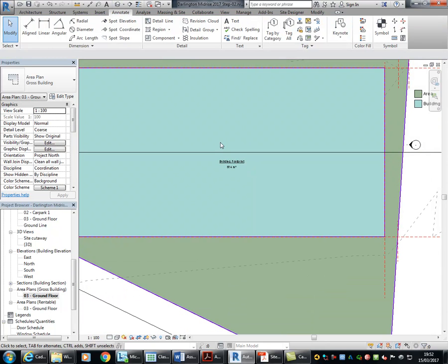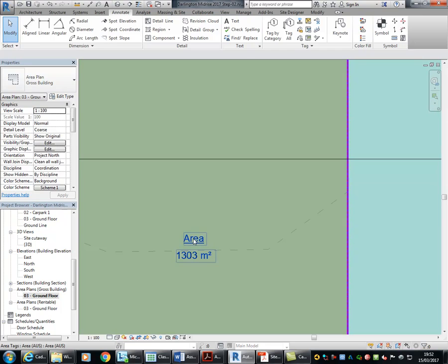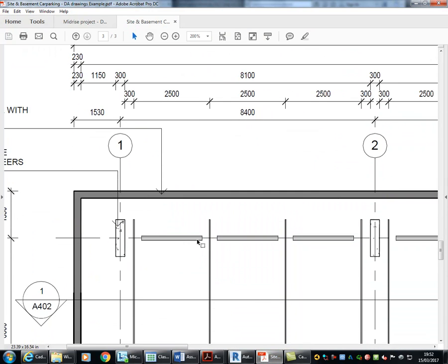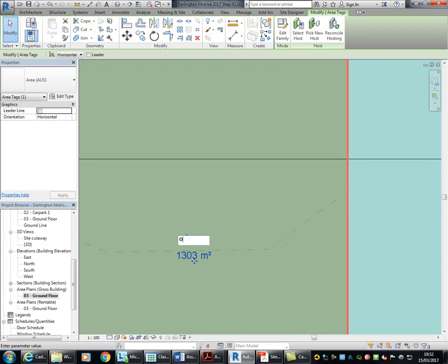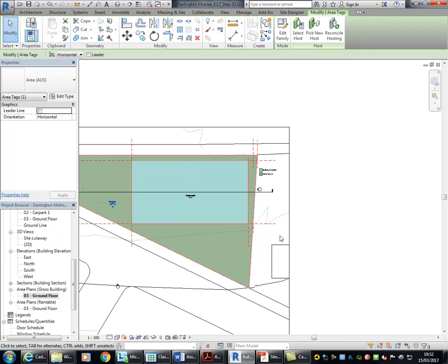And so notice it changes the colour because it's got its own name, and each name will have its own colour. So this area over here, which is called area, I can also rename that, and I'll just call it open space. And again, when I hit enter, it will change colour sometimes, but no, in this case it's kept the same. Those colours are basically random.